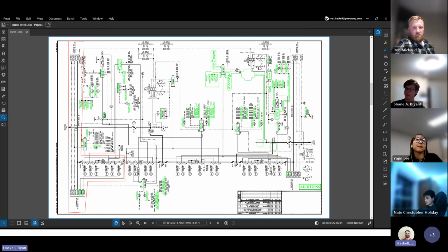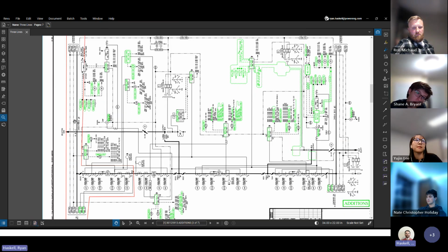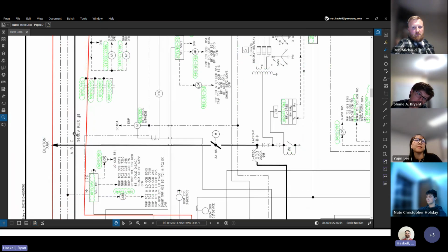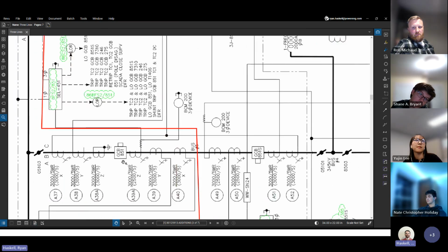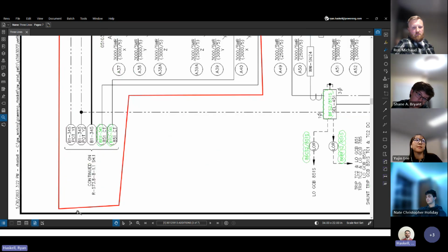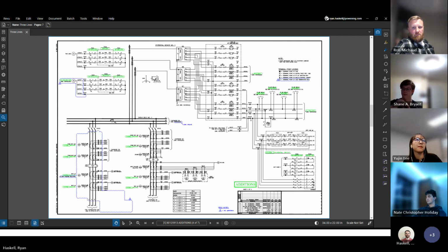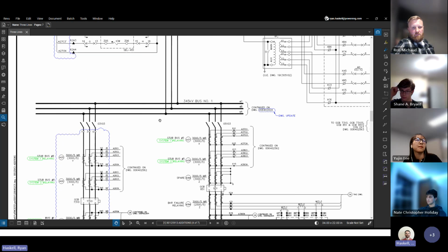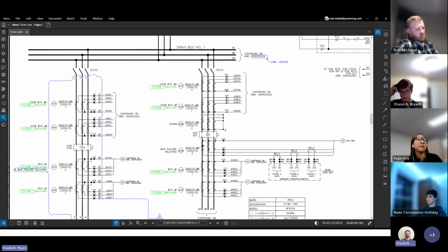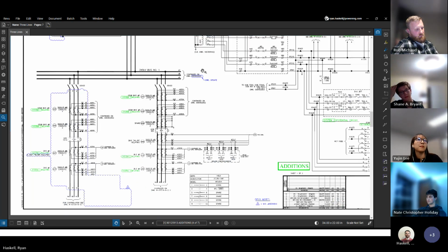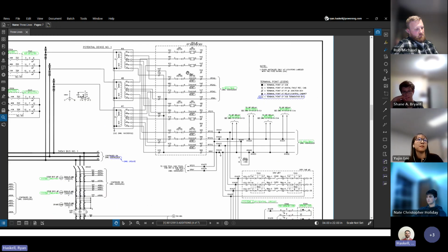Another project. This one was an overall relay upgrade project. And the section of the 3 line we'll be looking at corresponds to this section of bus on the left here, the 345 kV bus 1, and also includes breaker 851, as well as another breaker shown on the neighboring 1 line. And you can see the same equipment here, broken out by phase, CTs, and all the secondary connections for the relay.